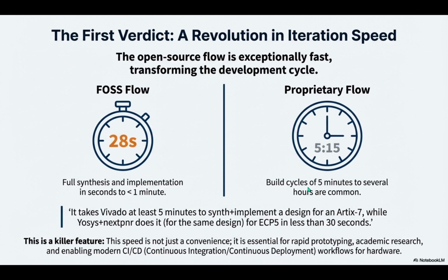And what's the proprietary comparison for that 28-second turnaround? Well, a proprietary tool like Xilinx Vivado commonly takes 5 minutes for even the simplest builds, and it can easily push into several hours for complex systems. So it's not even close. Not at all. The sources note that a design on an ECP5 using Yosys and NextPNR takes less than 30 seconds, where a similar design on an Artix-7 in Vivado takes at least 5 minutes. This speed is a game changer. It's what finally makes automated hardware testing, CI/CD, actually viable.